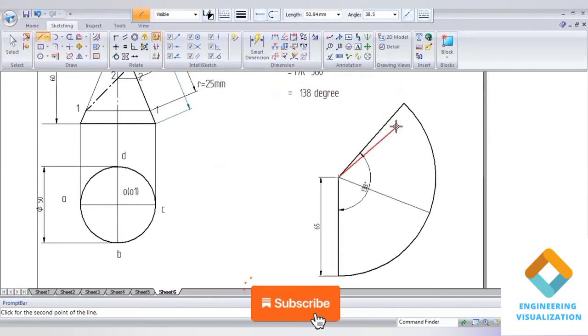Again, from those two extreme points, we should consider the length and cut the arc, so that we can divide these two equal parts into 4 equal parts. From this extreme point you can consider any length. Here I'll consider 50. So cut the arc. The same way you can do it on the other side also. Consider 50 mm.